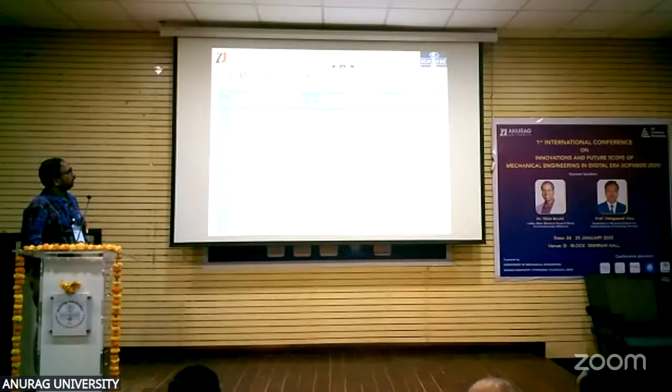Once the 3 parameters have been determined, they are listed, that is NP is equal to 3 and NP is equal to 4. With these values, I have determined the relative error for the output responses, the thrust force and the delamination factor. And the expected range is determined so that the obtained values lie within the minimum and maximum expected range.